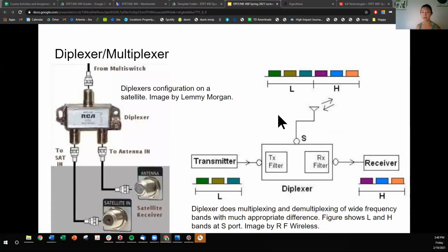It is often referred to as an RF power combiner/divider with added functionality of filtering. Broadband filters are used to pass appropriate bands at telemetry, the TX and RX path, where T is transmit, R is receive. A multiplexer is the extension to more than two frequency bands.